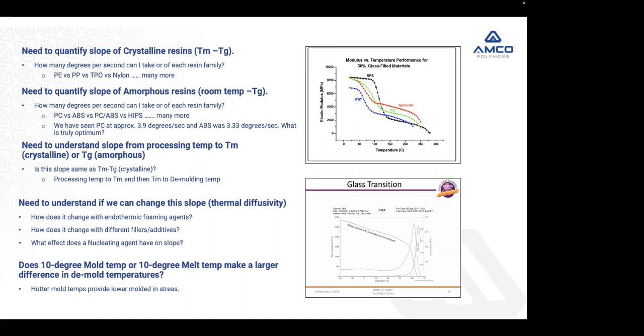And if it comes out 8 degrees colder, I can pat you on the back, say, you have efficient cooling. If you add 2 seconds, and I should be able to pull out 4 degrees a second, and a part only comes out 4 degrees colder, well, guess what? You probably may not have turbulent flow. There may be someone else that's doing conformal cooling or something different and has better efficient cooling than you do. But at least you know this now.